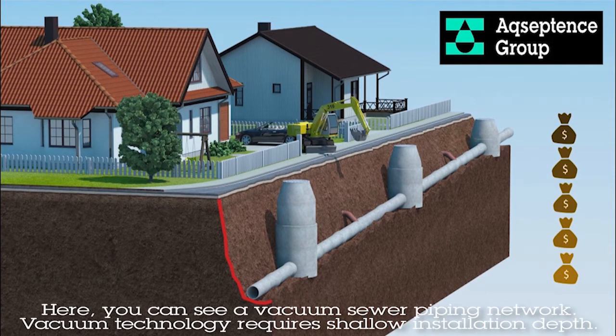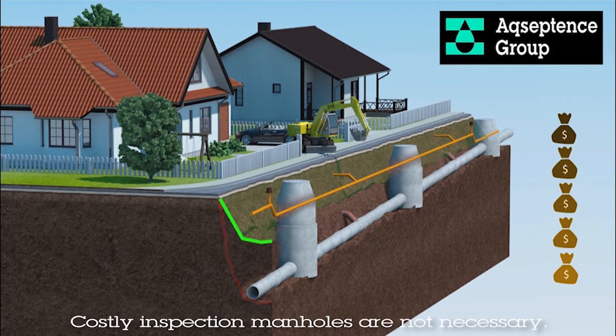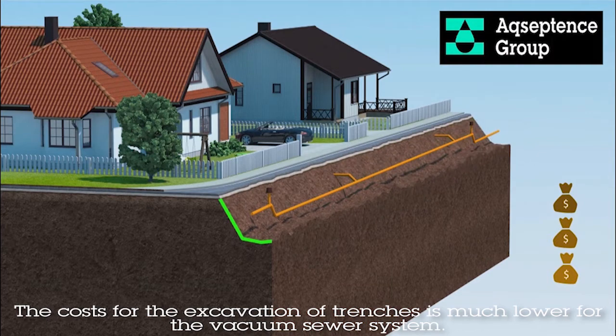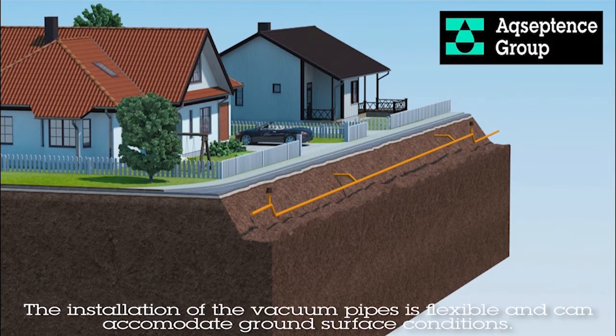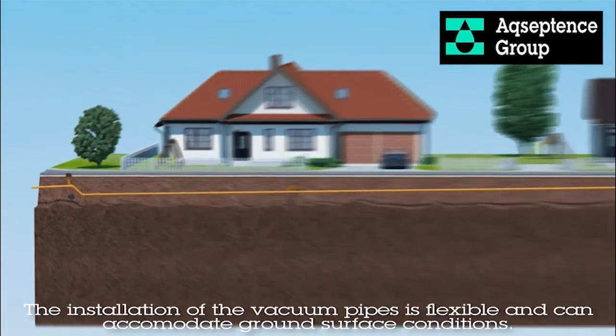Here you can see a vacuum sewer piping network. Vacuum technology requires shallow installation depth. Vacuum pipes are installed just below the frost line and in consideration of traffic load above the pipe. Typical installation depth is around 1 meter or 3 foot. Costly inspection manholes are not necessary. The cost for the excavation of trenches is much lower for the vacuum sewer system. The installation of vacuum pipes is flexible and can accommodate ground surface conditions.